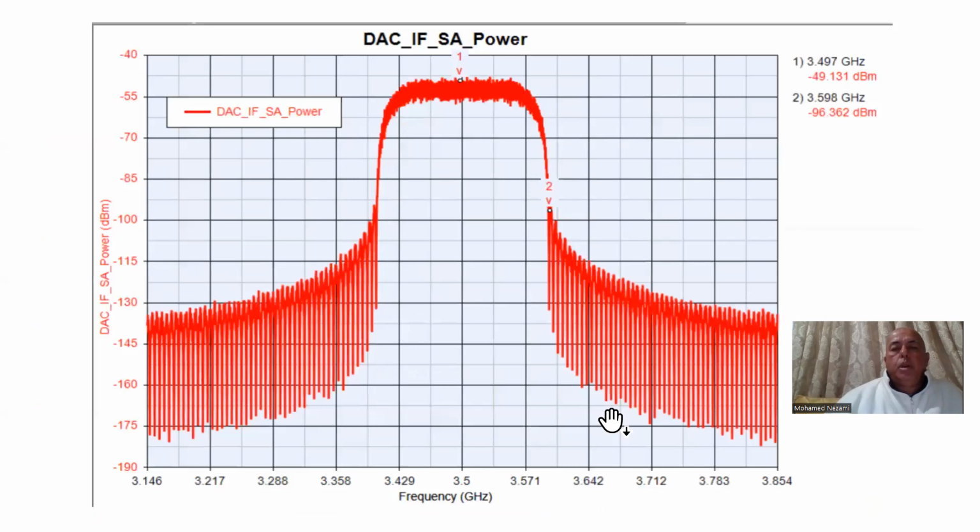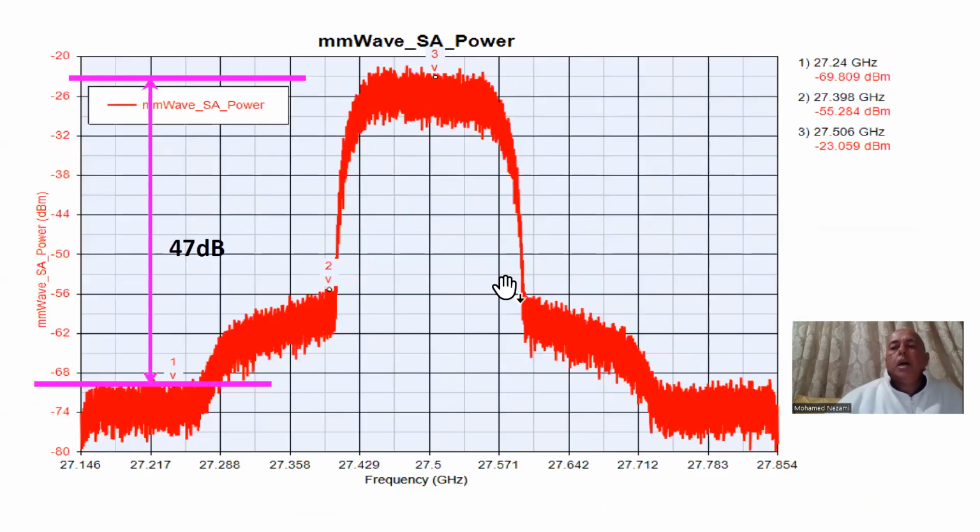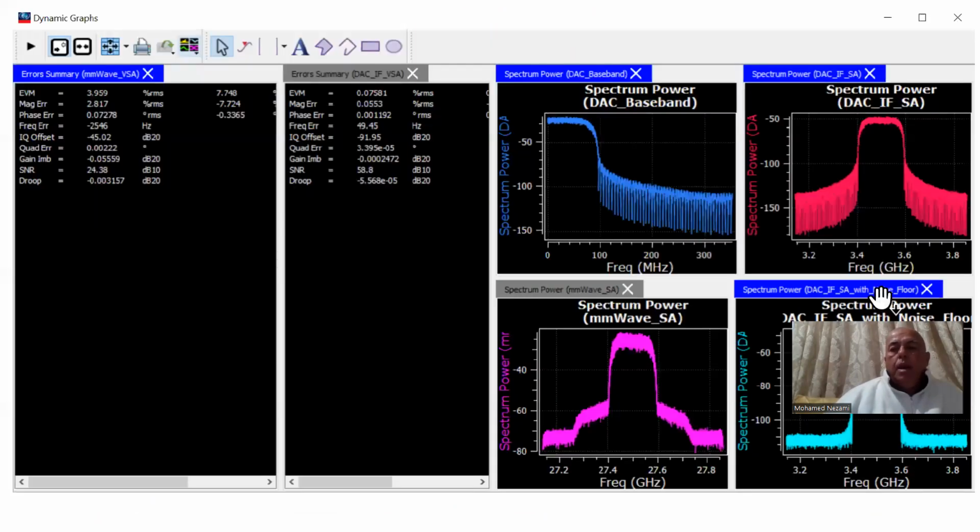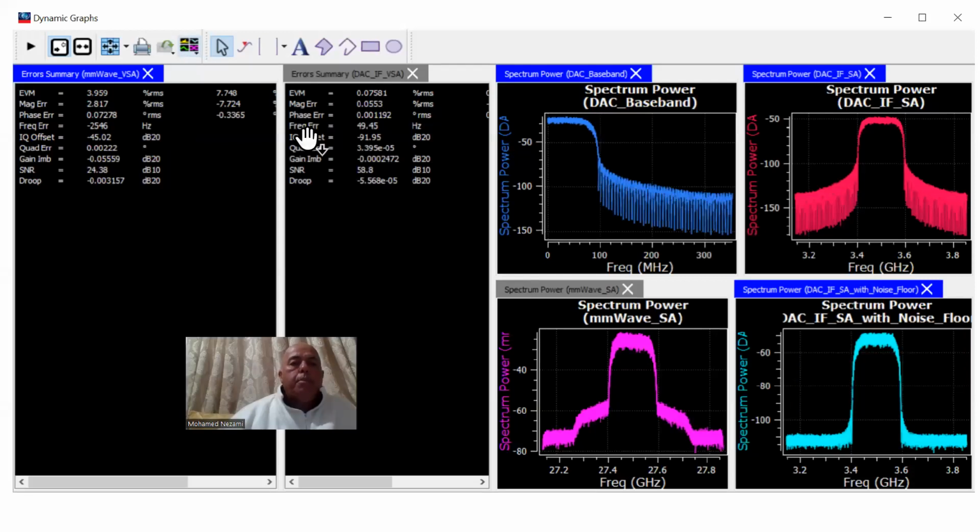And that's what we are getting with the actual live modulations. Then of course, we're going to monitor the EVM out of the DAC in here, which is almost ideal. This is because this is really before I set the noise spectral density. So it's almost ideal, 0 EVM. And the SNR, of course, is 60 dB. Here it is almost 60. Okay, that's what the system is seeing.